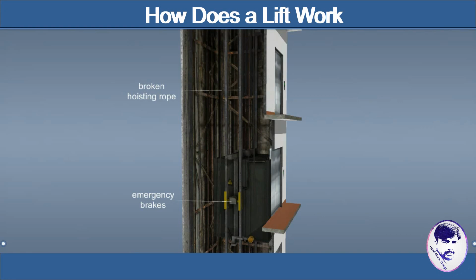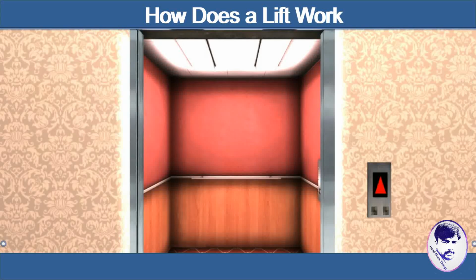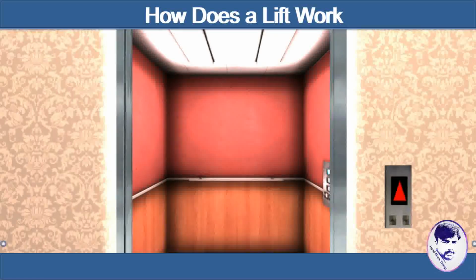Modern lifts are equipped with several safety features. Usually, multiple cables are used to hoist the cabin, each one of which is capable of holding even the fully loaded cabin's weight. If every suspension cable is broken and the built-in speedometer detects a speed over the safety limit, the brake system is activated automatically, fixing the lift cabin to the guide rails.